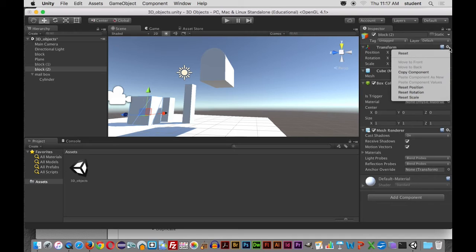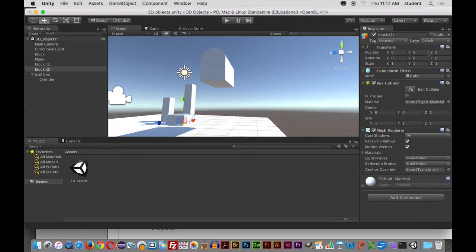I'm going to select reset, and that will reset it back to a cube. Notice it resets it to the 0, 0 position and back to the way the cube was. So if you deformed it in a way that you can't work with it anymore, and you don't want to redraw it or replace it or whatever, maybe try that. Or again, just try changing the XY scale or Z-axis, whatever it is that you might have changed.